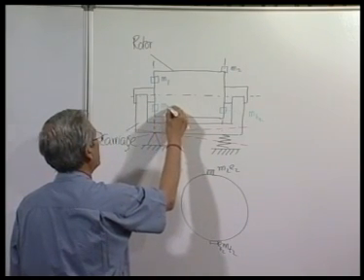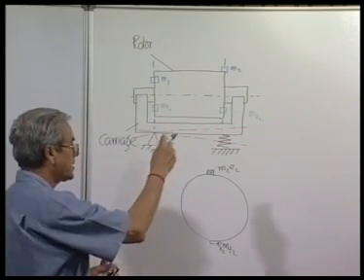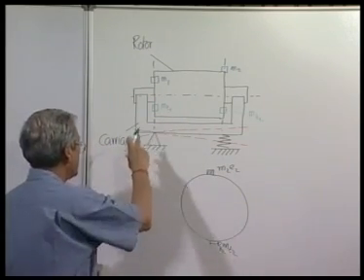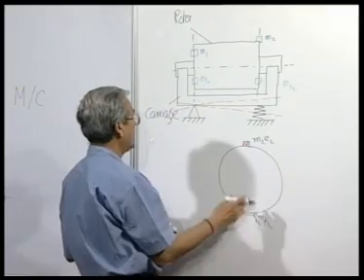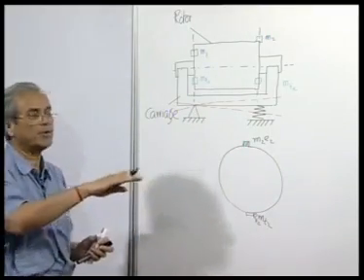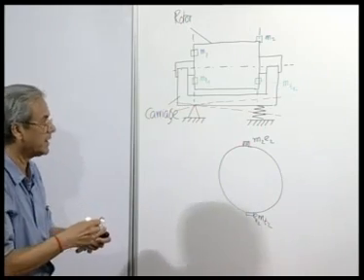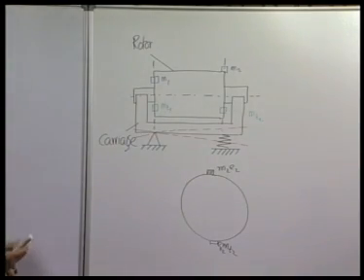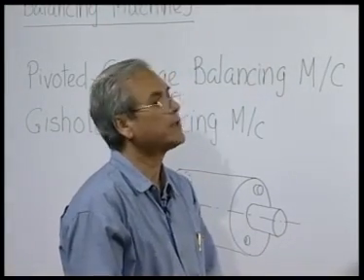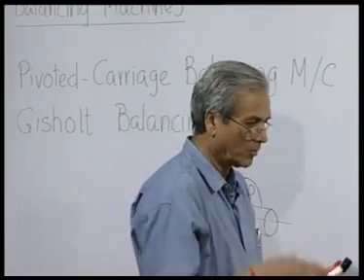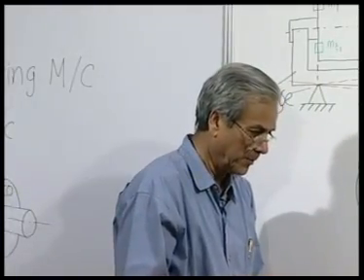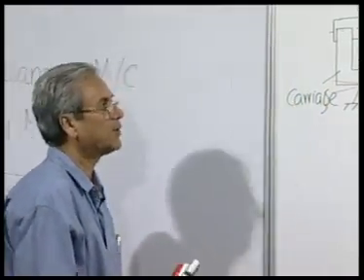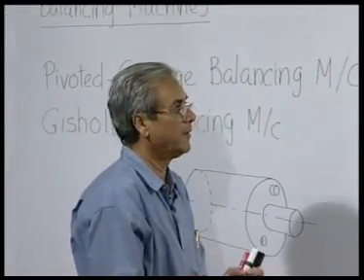So, we start with balancing or trial mass MT1. We first see which angular position this produces minimum oscillation, and then we adjust the product MT1 and U1, so that the vibration almost vanishes. Now, of course, you may say that this is purely a very crude arrangement, because we are doing everything based on our visual senses and tactile senses, but it gives reasonably good results, though the result may not be perfect, or balancing may not be absolutely accurate.